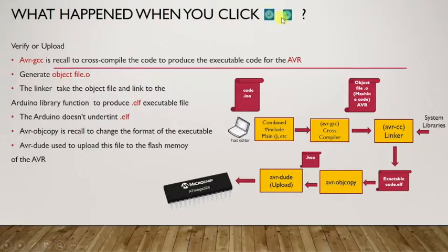When you click on verify or on upload, first your code.ino, the code you wrote on the Arduino platform, will first be combined with main, the #include files, etc. Then AVR/GCC is called to cross-compile the code. So the cross-compiler on Arduino is AVR/GCC. When you click on verify or upload, you must compile your code.